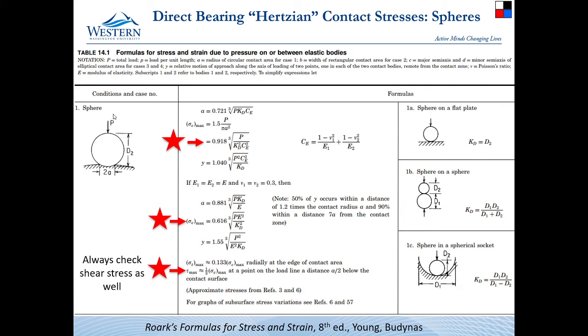Remember, when we start this also, we're going to have factors of safety in this value of P to make sure that we don't accidentally overload this and dent the material when we calculated that we weren't going to indent it. Well, what could we do if we want to make our shear stress value smaller? Okay, well, things that we could do, we could decrease the load. So we could figure out a way to decrease the load on our part.